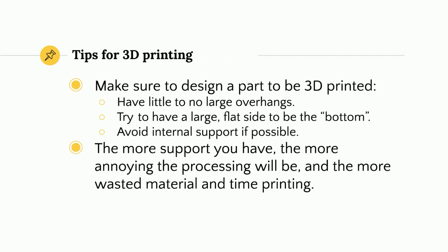Also, avoid internal support if possible. When I say if possible, I mean if you like going through pain and suffering, put some internal support. If you don't like that, then don't have internal support. Design your part around 3D printing. The more support you have, the more annoying the processing will be, and the more wasted material and time printing. I'll go over more tips about 3D printing in the last lecture.